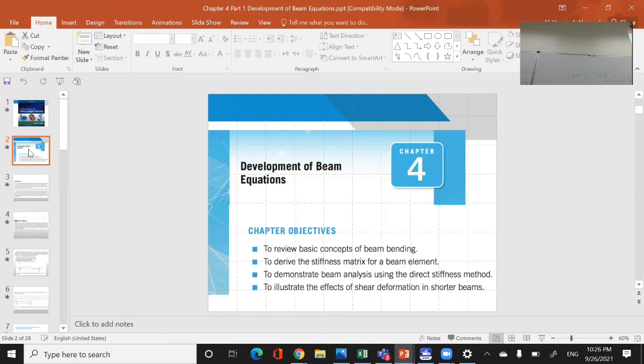For the beam, if you have a beam, and you have node here and node here, how many degrees of freedom for the beam? 4 or 5? Only 2. Only 2, which is deflection and rotation. Right? So how much? You have 4, right? Yeah, 4. It means the size of your matrix should be 4 by 4. Or no, 2 nodes, each node has 2. It means 4 by 4. Maybe V1, θ1, V2, θ2, right? Okay.